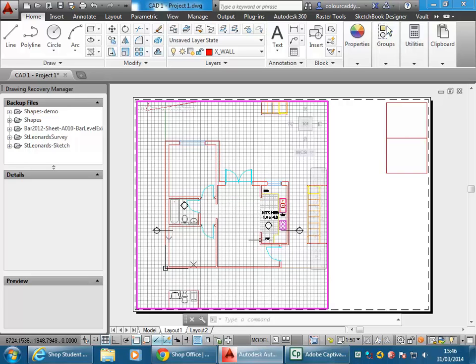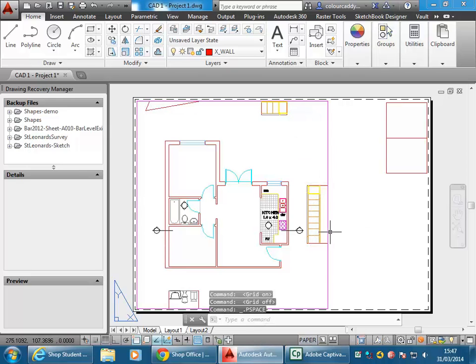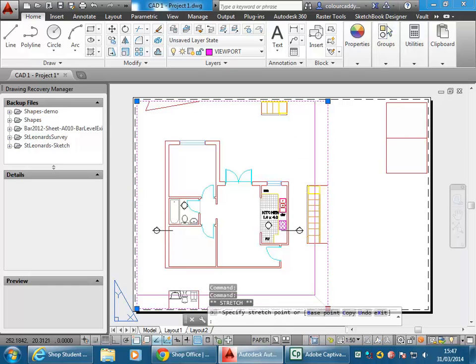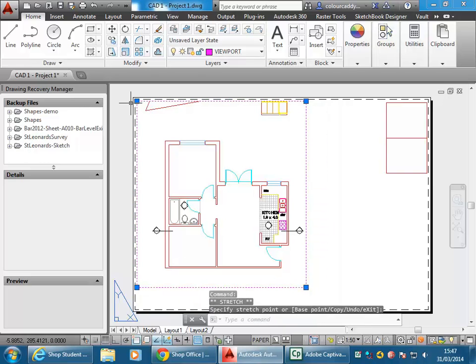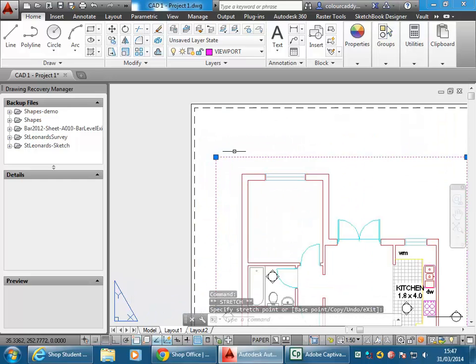And now, again, I want to go back and work on the page. I've finished setting the size of my plan. The grids may be a bit annoying or just hard to look at, so you can see down the bottom on the toggles there, there's one that looks like a grid. That is your grid button, the one with the square grid pattern. So clicking there toggles that grid on and off, only in the view because it's model. Now if I click model, it goes back to page, and I can keep adjusting the viewport so that it doesn't show all those extra things I have going around the plan. I want the elevations on a separate viewport.